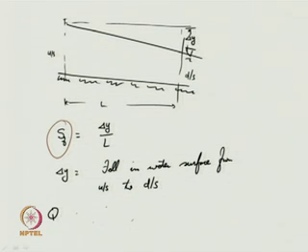The discharge Q can be given as Q is equal to K average into SF to the power of half, or root of SF. So, please note that we had given an approximation for the energy slope and we are substituting it. So, let me give this as a first approximation, and this is not the actual correct flood discharge from the channel. This is just a first approximation.